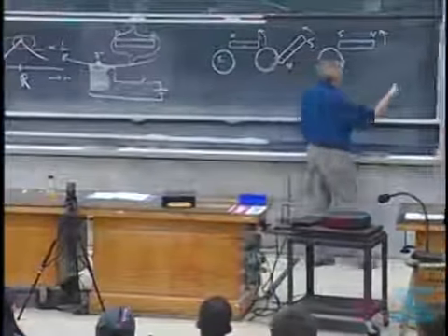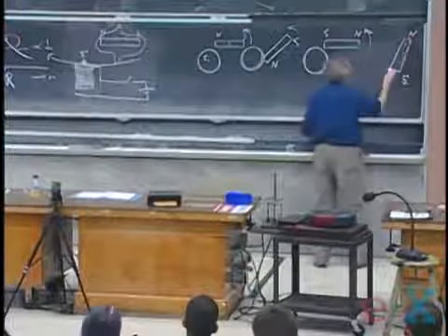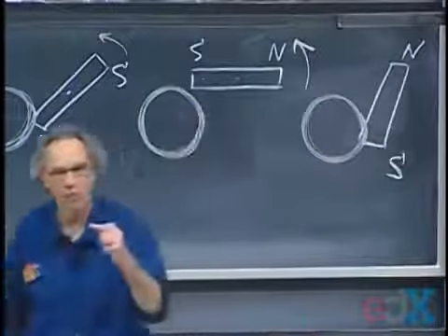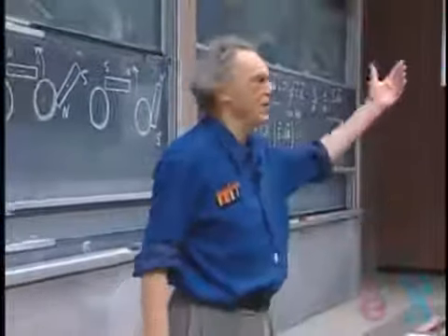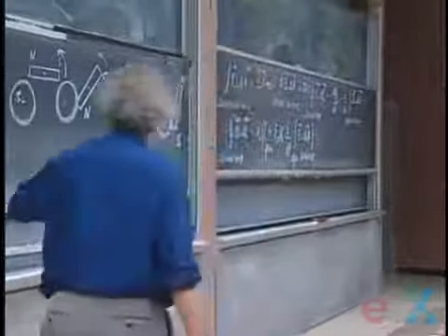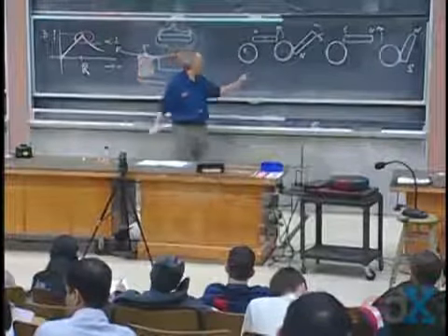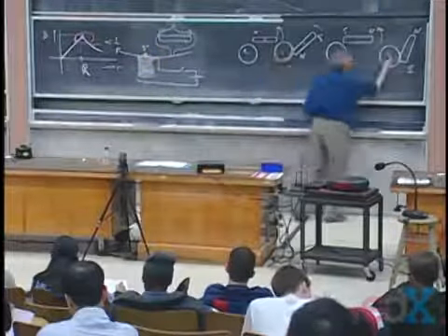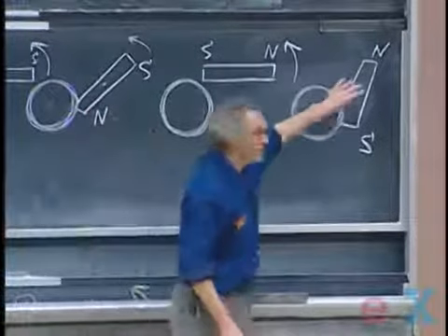But now, there comes a time that the south pole is leaving, is receding. And so let us have here our coil. A south pole receding is exactly the same for Mr. Faraday as a north pole approaching. And so now the EMF is in the same direction in the coil as it was here. And so now the transistor says, "Youppi, that's fine. I close the switch and I'm going to run a current." And so this becomes a south pole. South pole and south pole repel each other. So now the thing gets a kick again.